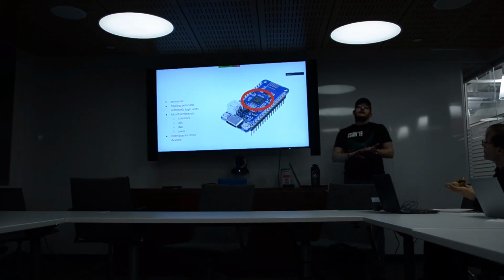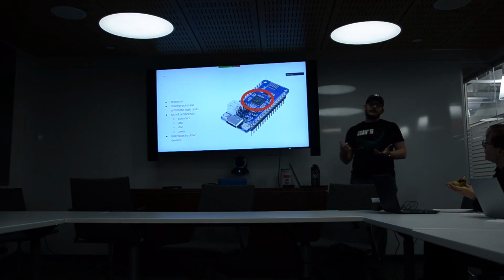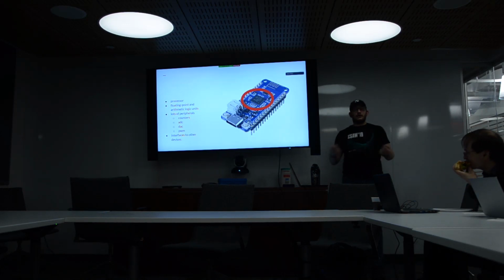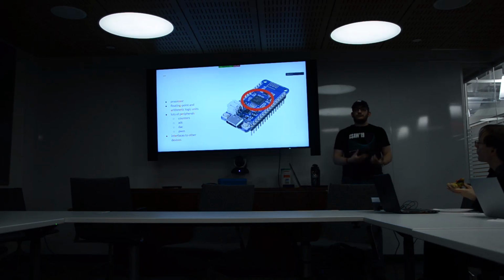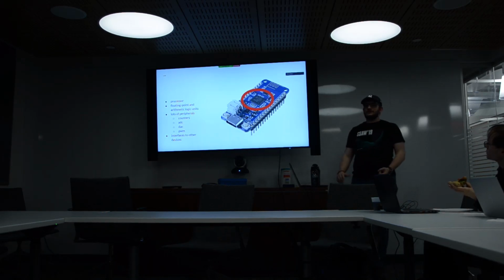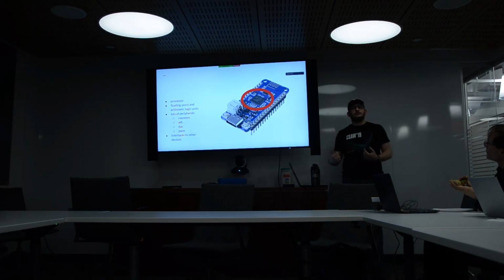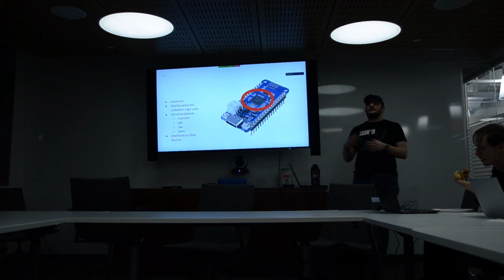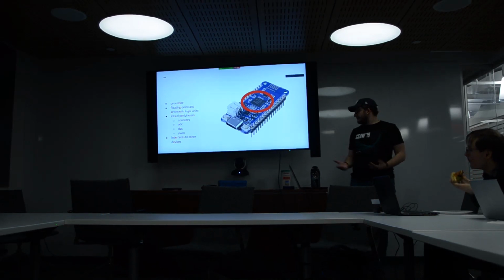An ADC is an analog to digital converter. So if you are building an IoT device that's supposed to determine whether or not your plants are watered enough, right? You would have a sensor that gives you an analog output that tells you how damp your soil is. You need some way of reading that. So a lot of microcontrollers have analog to digital converters built in that can translate a 5-volt signal to a 1024 binary value, and there you go, that's your value.